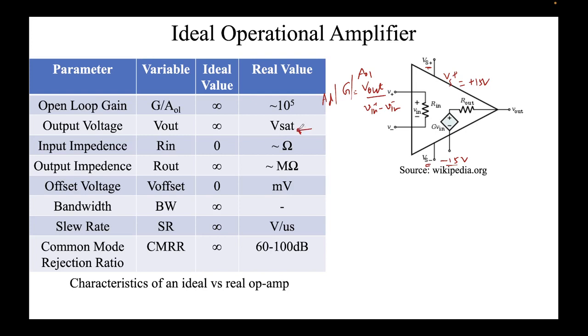Whatever the output voltage is, it will saturate. Let's say if VSAT is plus 15, it will saturate at plus 15 or minus 15. It cannot go beyond that. This is very important. We'll see in some problems how it's used.